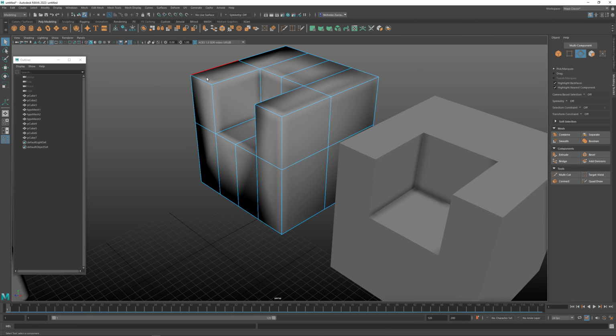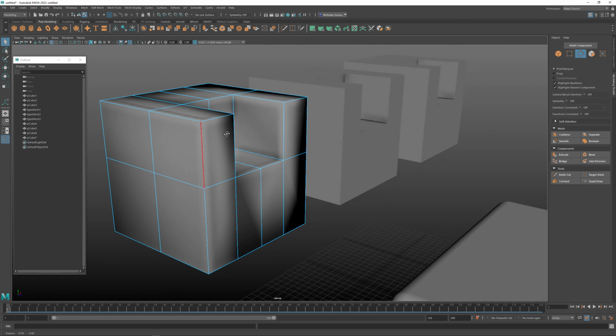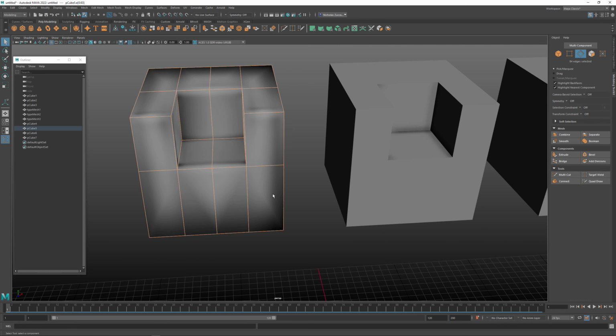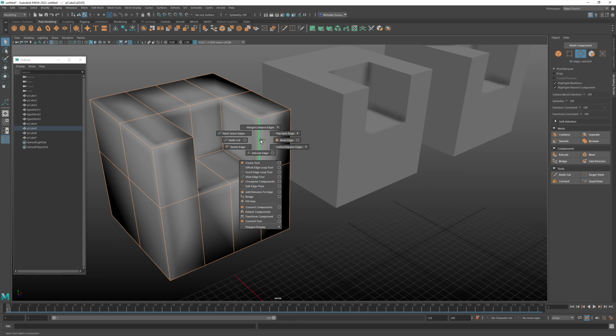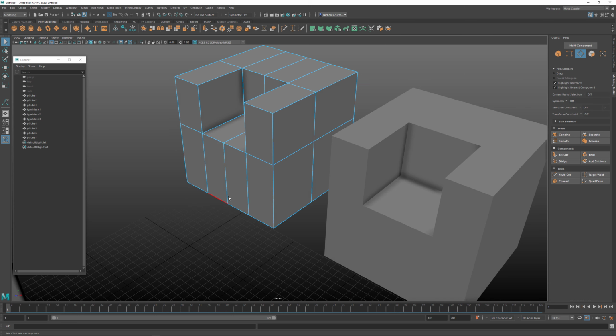So it tries to shade between this face and this face. All the faces are now starting to try to shade across there, so it produces this kind of look, and sometimes you're going to want that. Now if we select all of our edges and Shift right click and say Soften Harden Edges and do everything hard edge, it works, but we're actually even doing hard edges between this edge, this edge, this edge here.